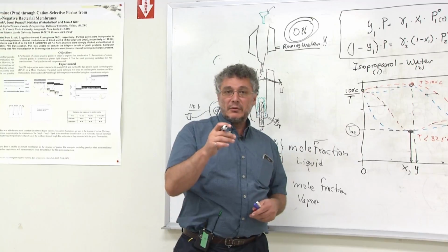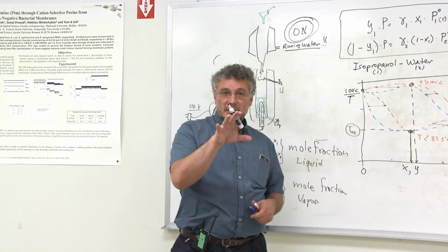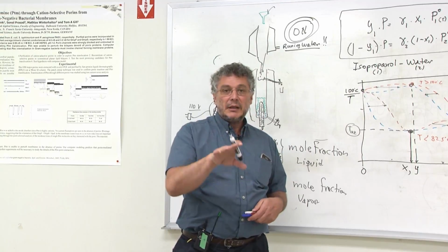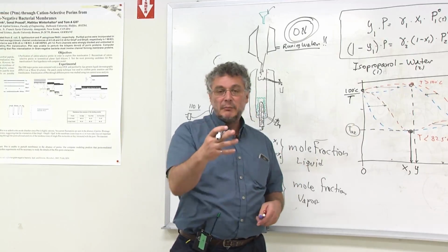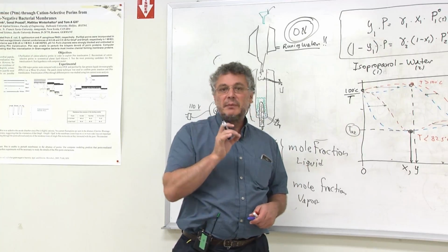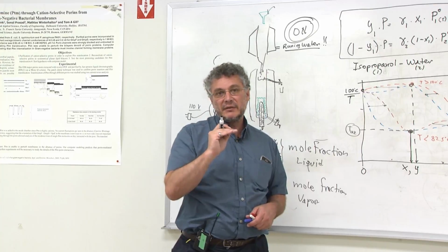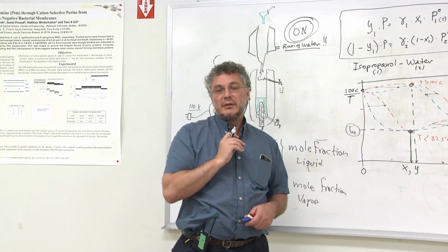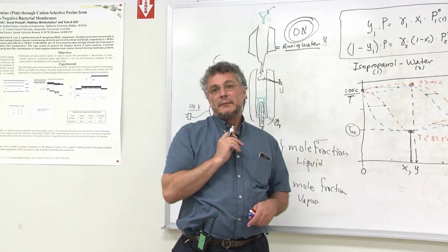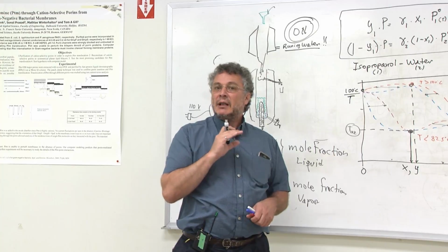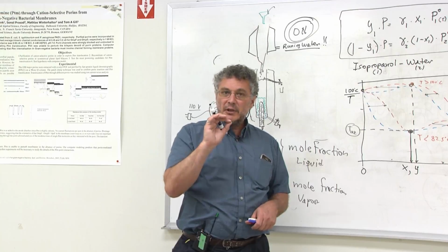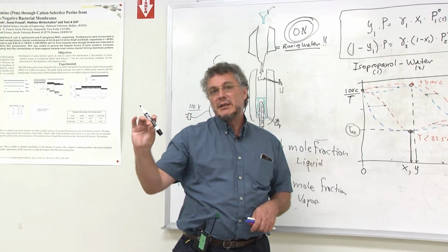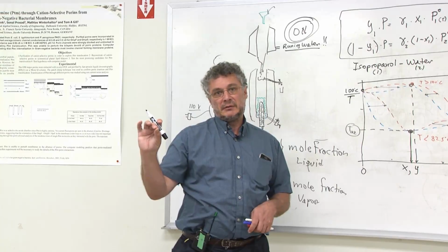I'm not going to go into all the details yet on how to operate it, and we'll do that with the actual refractometer rather than here. But basically you need to place a drop of the liquid on the surface of the refractometer, close the prism of the refractometer, and the refractometer will be at a controlled temperature. So that little droplet will very quickly equilibrate to the temperature of the refractometer.